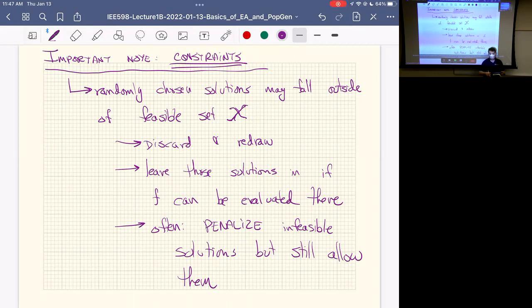Also, in process control, there's soft constraint enforcement, and I believe they follow a similar logic. Yes, the idea of soft constraints is very much related to this. In process control and other versions of control, we often penalize constraint boundaries as opposed to making hard constraints. We call those soft constraints, and it has a similar feel.